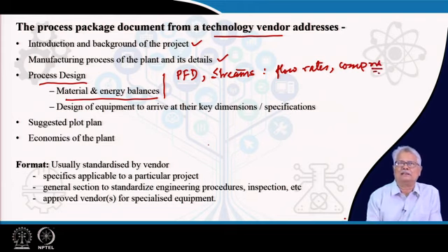So, if you look at the PFD with the flow rates and composition of the streams marked on it, you will understand what exactly is the flow between the different process units, different equipment, and what exactly is the energy transfer involved in the entire process itself. You definitely can have an idea of the amount of energy which is required for your process, which is a very important parameter for your client to know, because he is the one, while he operates his plant, who has to get and arrange for it.